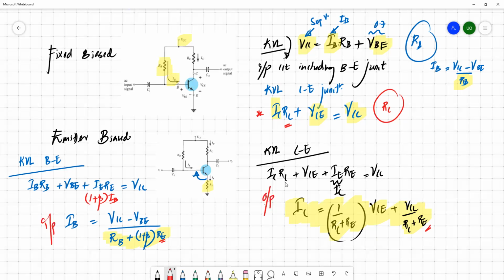So this RE acts as a kind of feedback mechanism between the output circuit and input circuit. With that, you can manage uncommon behaviors appearing on the output side by informing the input side through this RE to adjust its Q point values.